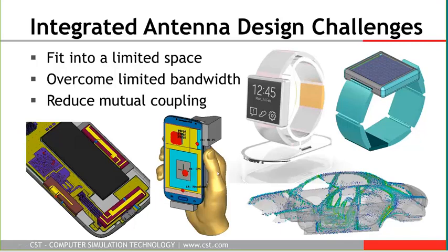And as I said, communication devices such as mobile phones are quite portable devices. Therefore, these antennas need to be placed on a common ground plane, and they are quite close to each other. Therefore, we need to consider mutual coupling between these individual antenna elements. All these problems can be tackled using modal techniques, or more specifically, characteristic mode analysis.